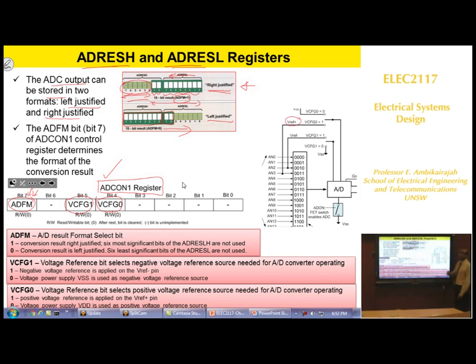If you want the reference positive voltage to be connected to the external world, that's here, you set that equal to 1. That means that pin will be connected and set up a reference voltage for the ADC converter. If you decide that's not what you want, and you want to set it to the supply voltage, you set this bit to 0, and this pin is your supply voltage. So this line becomes ineffective. You are not using that line at all.